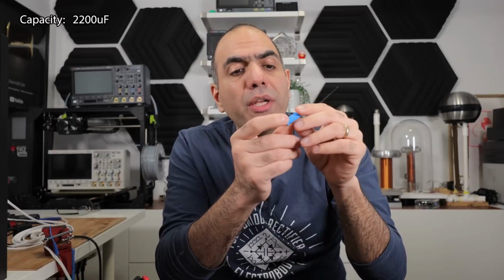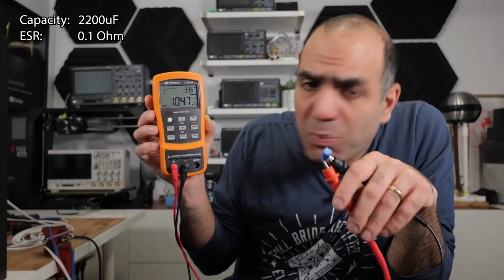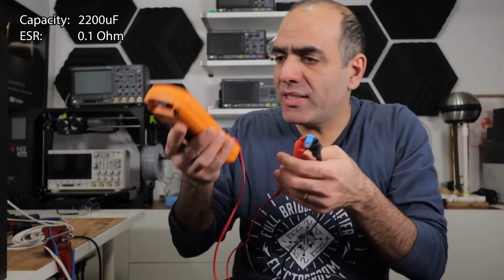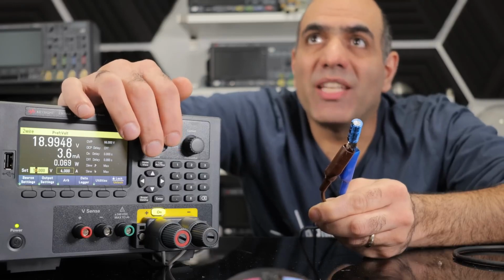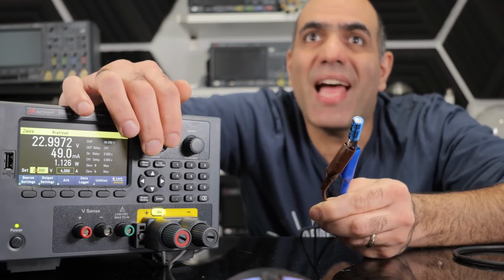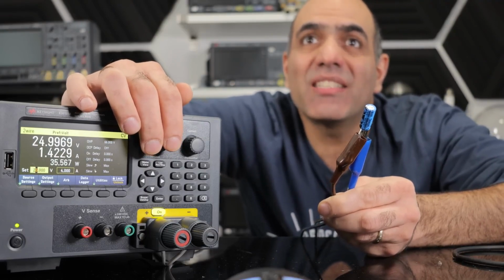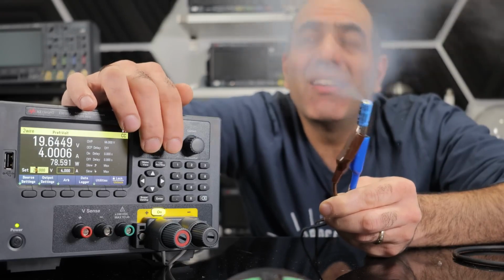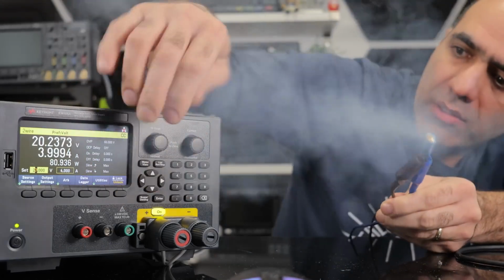This is a healthy 2200 microfarad capacitor with an ESR of around 0.1 ohms and the parallel resistance is over 6 mega ohms. So when I overload the capacitor and it bulges, those tiny grooves on the top break open, allowing the release of the pressurized gases, and this will save the capacitor. Woohoo. Well, stop it.